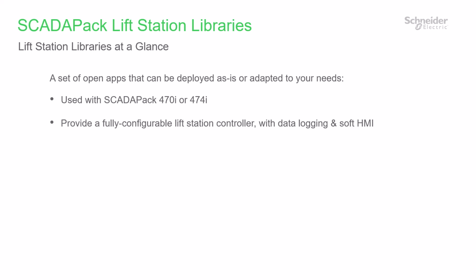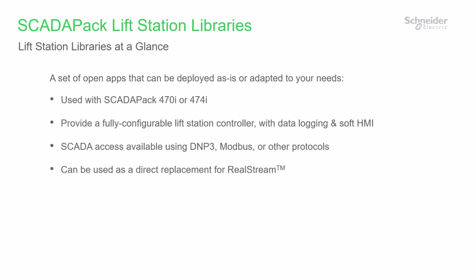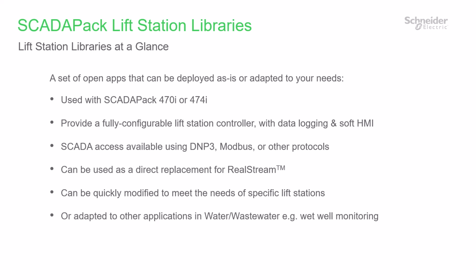They provide you with a fully configurable wastewater lift station controller, complete with data logging and soft HMI capabilities. SCADA system access is available using DNP3, Modbus, or other protocols. You can use the libraries as a direct replacement for Schneider's retired RealStream offer. You can quickly modify the library elements to meet the needs of specific lift stations, or you can adapt them to other water-wastewater applications, for example, wet well monitoring.